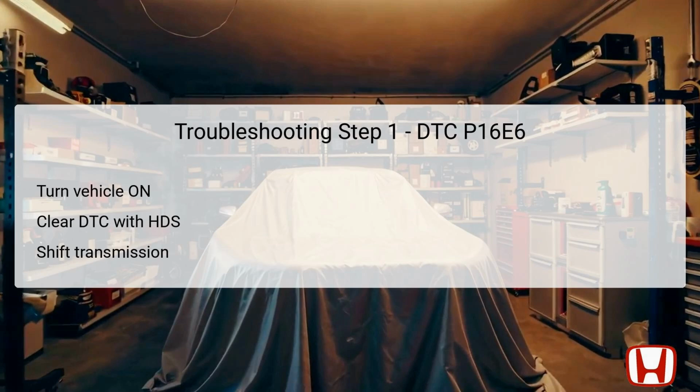The first step in addressing DTC P16E6 involves verifying the problem. Start by turning the vehicle to the on mode, allowing the onboard computer systems to initialize. Following this, it is critical to clear any existing DTCs using the Honda Diagnostic System, HDS, which helps create a clean slate to accurately assess current issues.